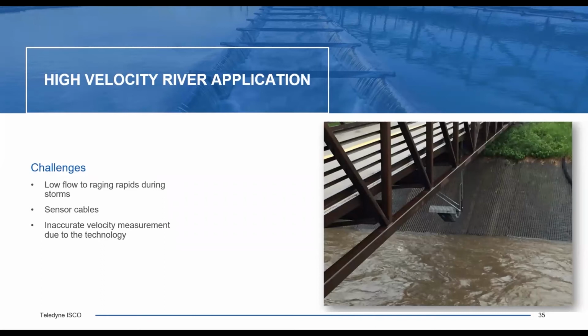So as I mentioned earlier, the continuous wave Doppler style meters are very good, but as that water level gets deeper and deeper, they will tend to be less accurate as the flow goes up, exceeding about 2 feet. So you need to determine what your accuracy requirements are, and do you want to put a sensor with a cable in there? Benefits of laser flow.